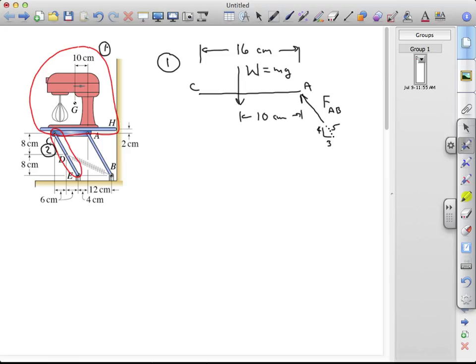Then we have a pin support at C. And I'll represent these forces CX and CY this way. That's our mixer platform free body diagram. For CDE, we have first the equal and opposite forces from C. So if on CA, CX and CY are as shown, they're equal and opposite on CDE. So CY is like this, and CX is like this.